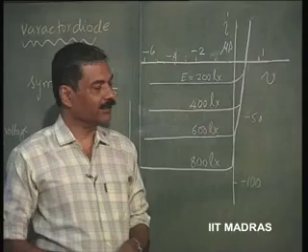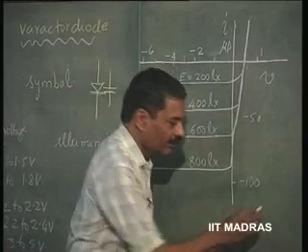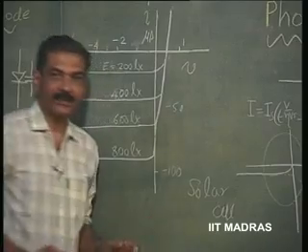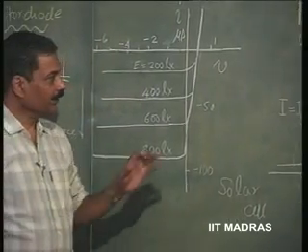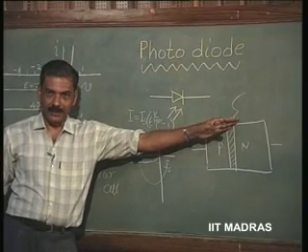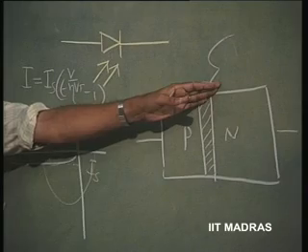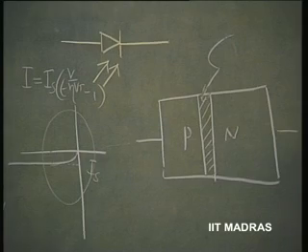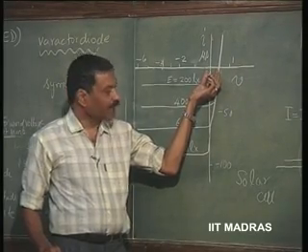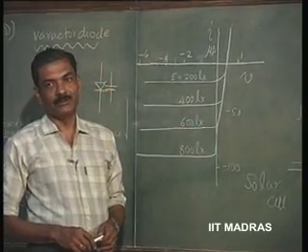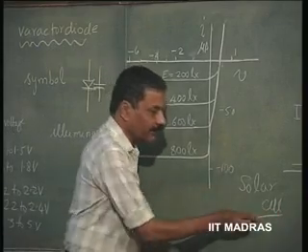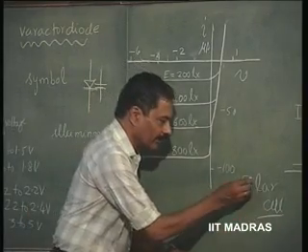That function of this diode, the photodiode, is known as a solar cell. That battery, which you can sustain by giving an external source of energy to the junction constantly, has a junction voltage for silicon typically around 0.5 V, and you can now have a battery of your own. So, this is an important application of the photodiode as a solar cell.